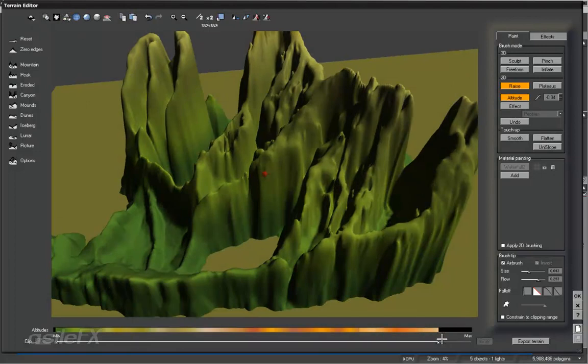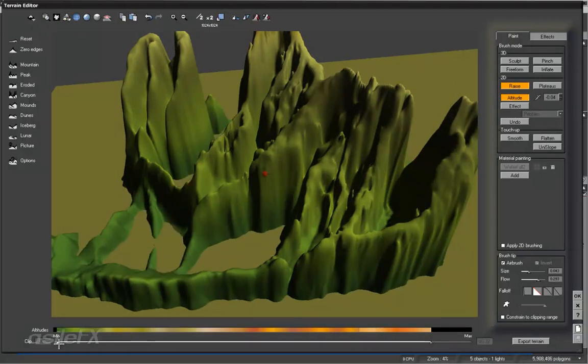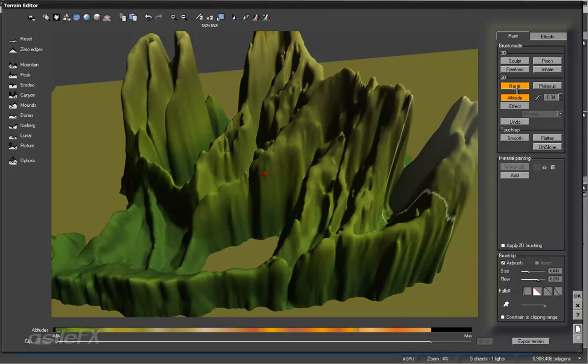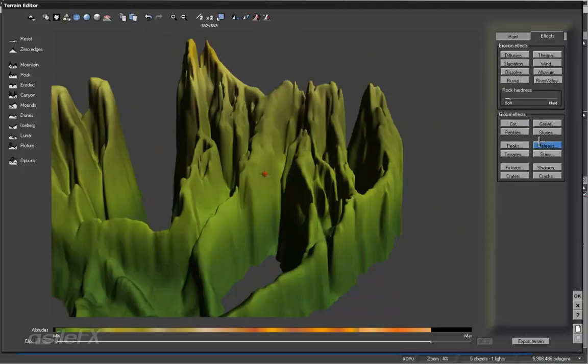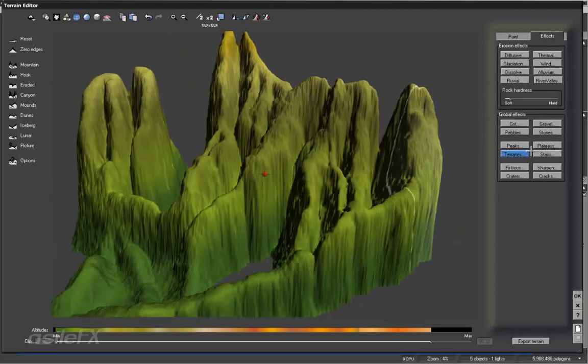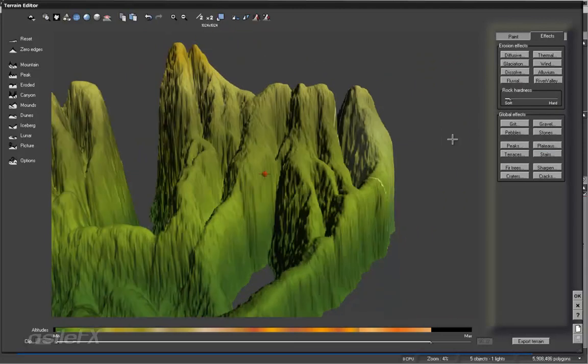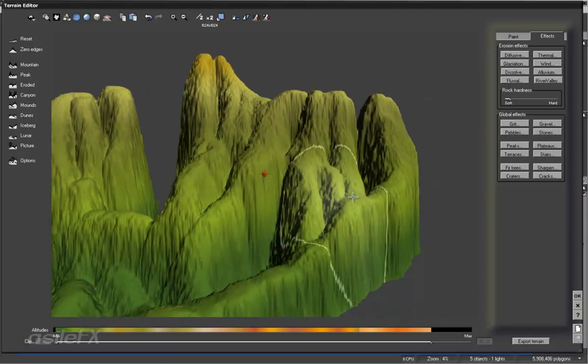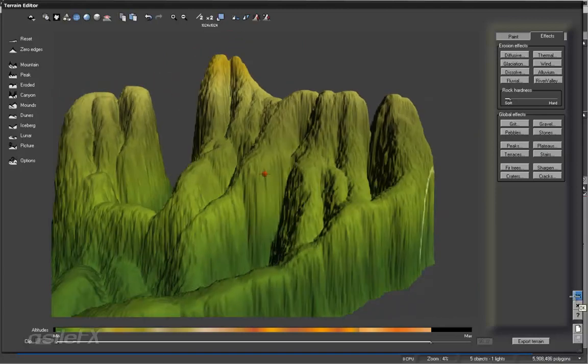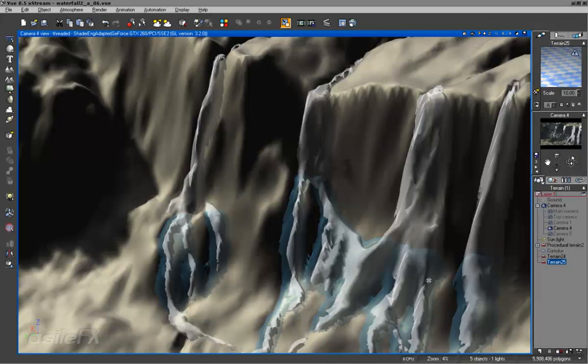So what we can do, because we can't use this exact same one in this same layout just because it's too fine, is go back to the effects and use Plateaus in order to spread that out more. And we still need to go back and modify the original water surface as well, because it does have too smooth of areas.